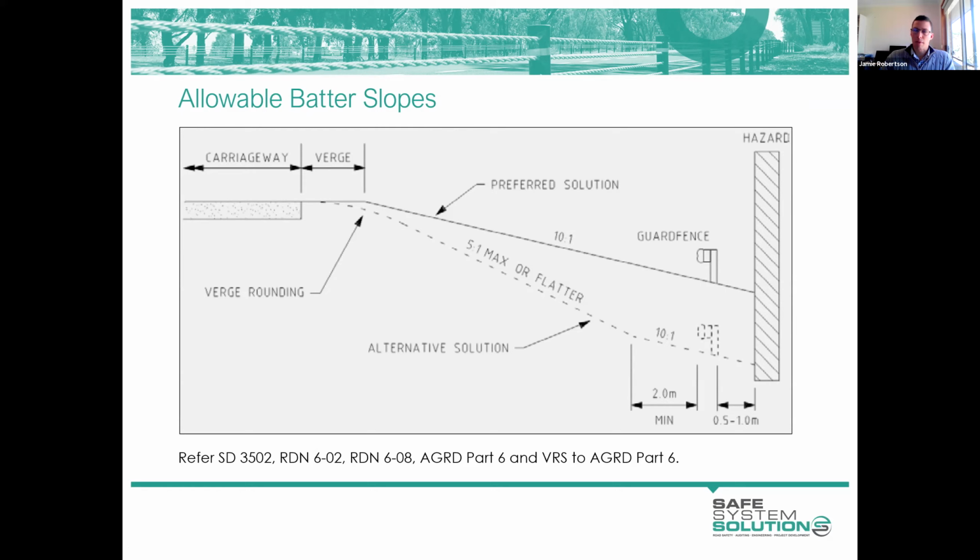There is another requirement to be mindful of where we have slopes in the order of 5:1, 6:1. That's to do with proximity of batters to hinge points. It comes from AASHTO, which says don't locate a barrier within, I think, 3.6 metres of the hinge point where you've got a slope of 6:1 or steeper.